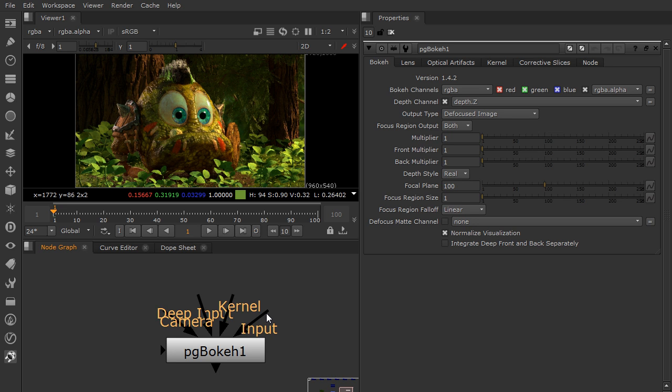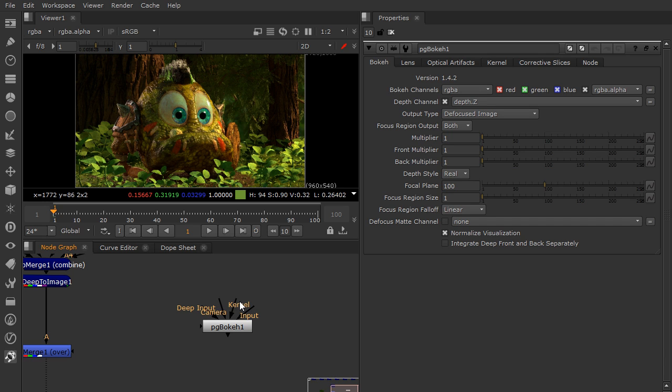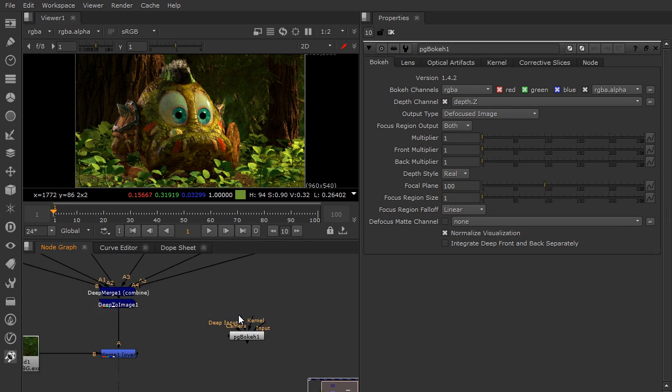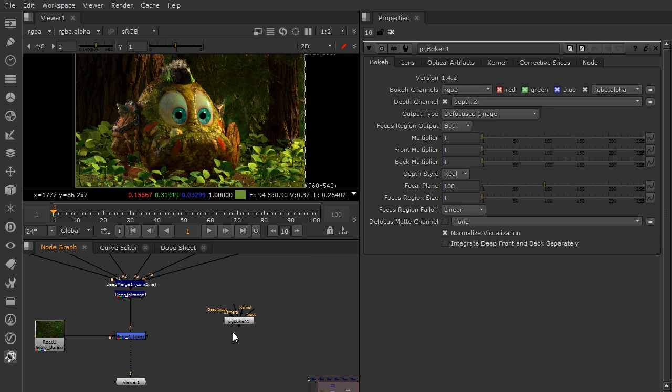based on how a normal blur node, like a Gaussian blur, just takes neighboring pixels and then averages them together. In the case of a convolution operation, you're actually blurring the image based on a shape, and that shape would be the kernel input. We're not going to use a kernel in this case, but I just thought I'd explain it in case you wanted to try and match something. Because if you have a very specific look in a project that you're working on, and you can see very clearly a certain shape when you have a defocused image, and you want the defocused areas of your visual effect shots to match that exactly, then you would definitely try to use a kernel shape based on a reference image from an actual out of focus area from the real lens.